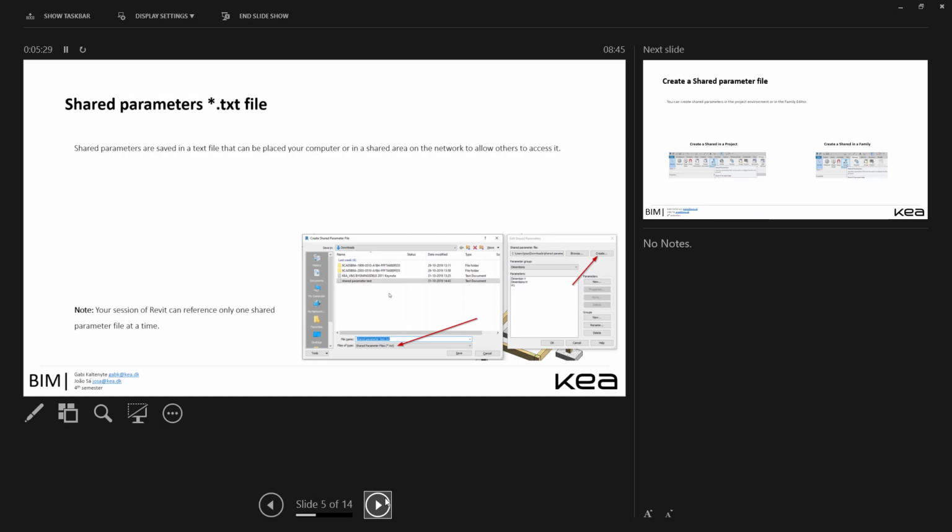This is the way it looks. The shared parameters in here. So this is the file, and these are the parameters that are available. When you create a project parameter, I don't know if you remember, but you have the first option, project parameter, and then you have shared parameter at the bottom. You are creating a project parameter based on a shared parameter. So what we say is that we are taking this idea. Okay, somebody had this idea of creating this parameter. I'm using this idea to create my own. So then there is consistency across all families and all projects. Make sense?